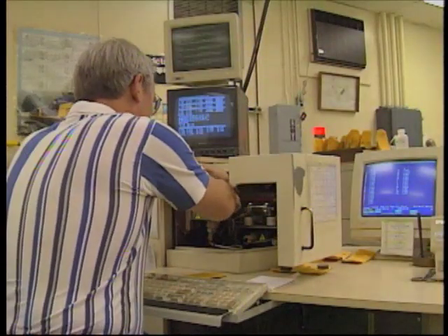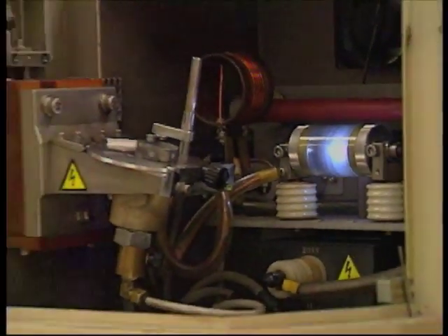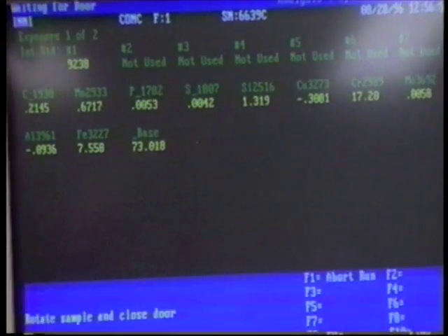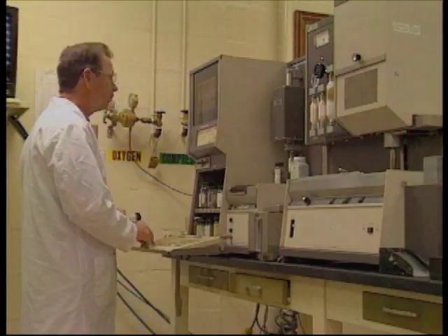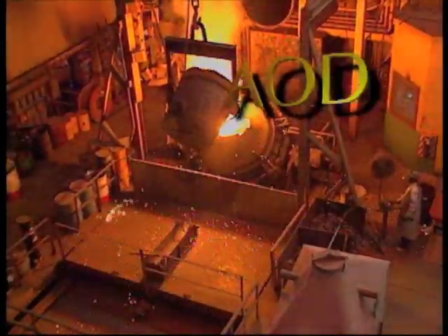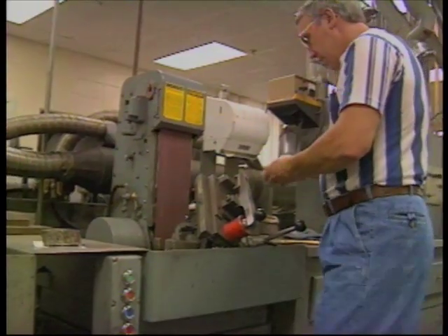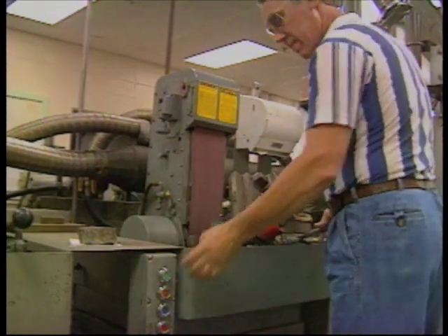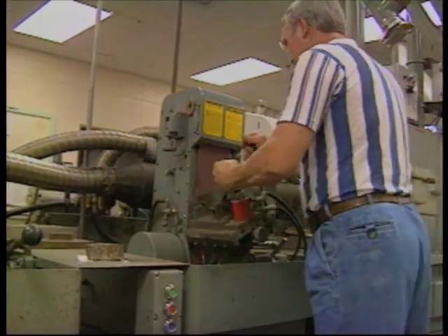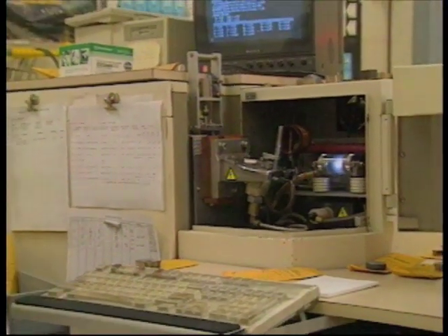Once either type of furnace has melted the steel, final adjustments are made to the composition. A spectrographic analysis at the foundry's lab is used to make sure the steel composition in the furnaces is the specified alloy for the application. Argon oxygen decarburization, AOD, is a precise secondary refining process that is primarily used for stainless steels. It may also be utilized for applications that require special attributes of toughness, ductility, precise chemistry, and microstructure.